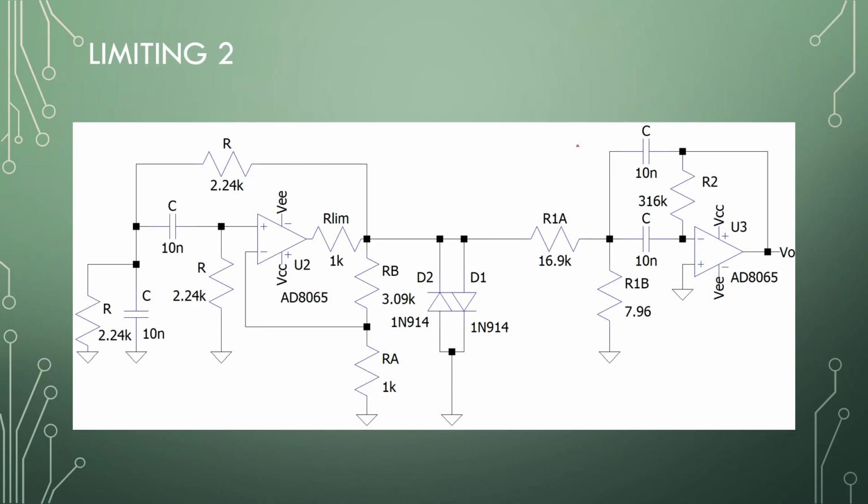Then you can design a second bandpass filter with a high Q value and take this 700 millivolts and convert it to whichever output you want, 5 volts or 6 volts, 4 volts, whatever you want, and filter the output from this now oscillator, which is limited, so we will have kind of block waves. Put it through a bandpass filter and we will have nice sinusoids coming out.